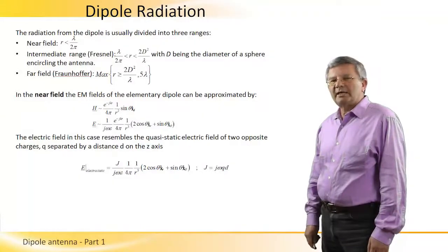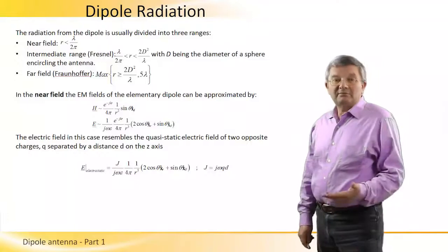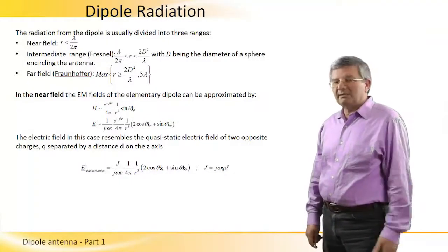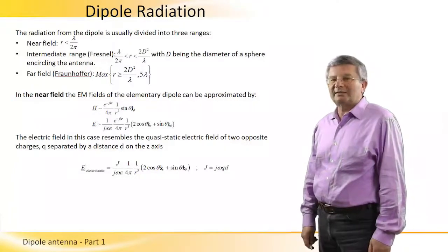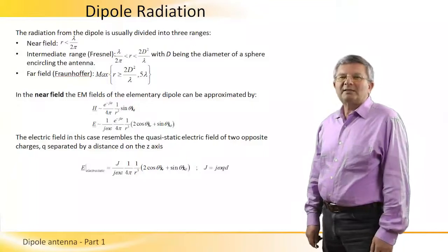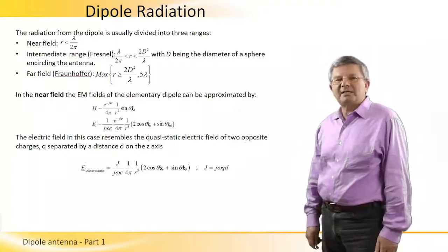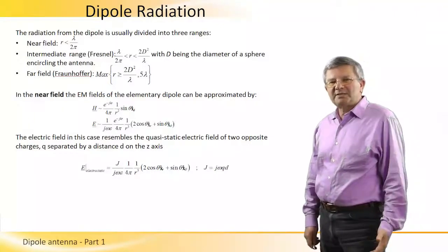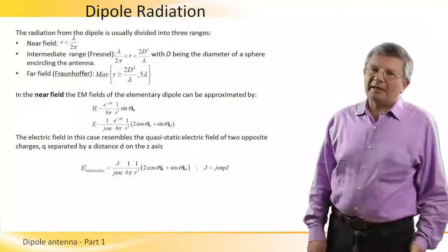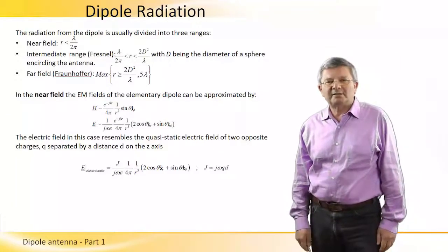Therefore, we can conclude that the near field of the dipole antenna, and we can extend this concept also to other antennas, is very much related to the quasi-static electric field of the problem. And this helps in many cases to understand the physics of the behavior of the electromagnetic fields in the near field of the antenna.